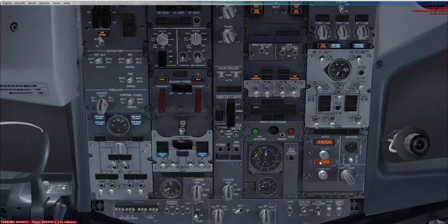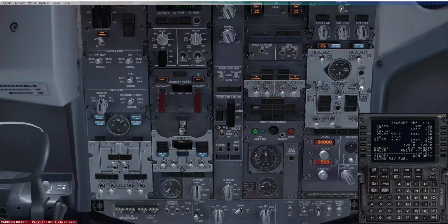Pack left and pack right off, because the air from that is coming from the APU, and we need that air instead to start the engines. Check. Throttles at idle. Start pushback. We're going to go directly back 25 feet. Probably should have gone a good bit further.